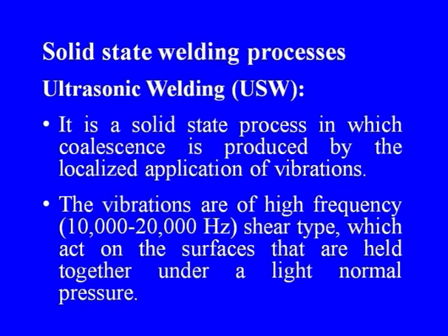Ultrasonic welding process is a solid state process in which coalescence is produced by the localized application of vibrations. The vibrations are of very high frequency, in the order of 10,000 to 20,000 hertz, and they are of shear type, which act on the surfaces that are held together under a light normal pressure.